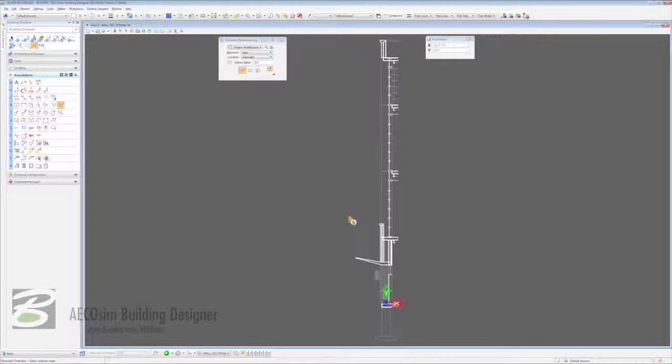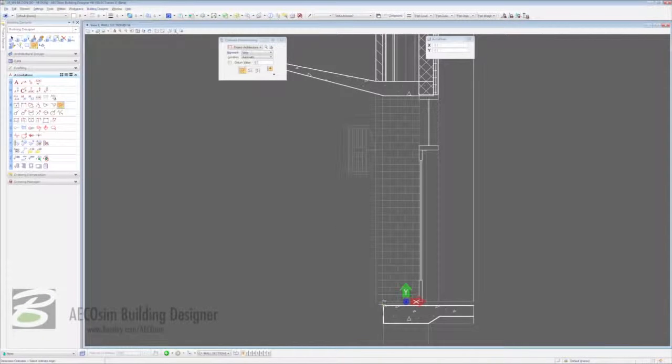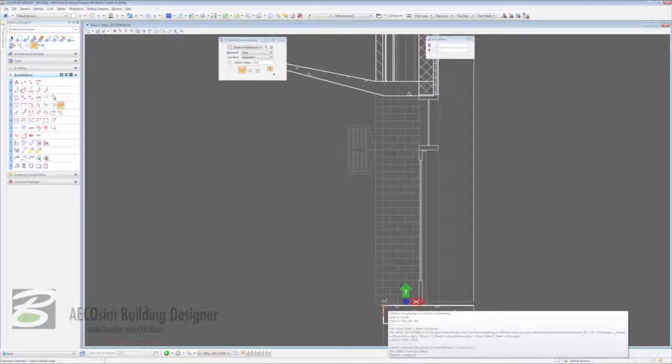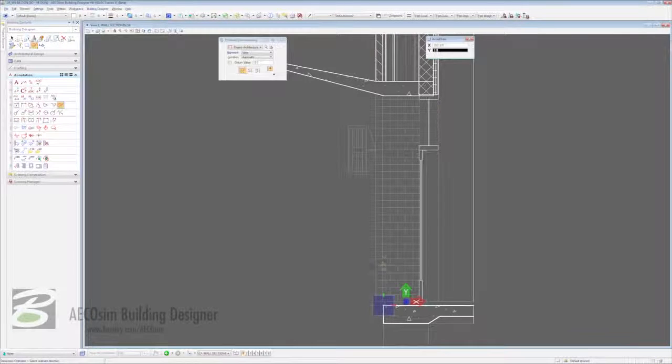First thing we're going to do, we're going to zoom down here to the top of our slab here. We're going to click once with our mouse. After that, we're going to go up in this direction. We click again, and then we bring it out, because what we're doing now is we're giving the elevational heights for this section that we see here. We're going to bring this out here, and we're going to click once, and you'll see we're at 0 feet.